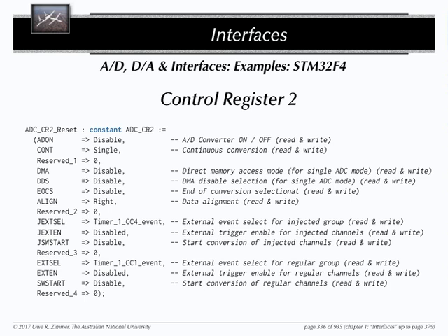If you take a local copy of it, manipulate all the elements which you want to change in your local copy, and then write back the whole register in one assignment, then you write the whole word in one go, and you don't have these atomicity issues which you may have had otherwise. Right.